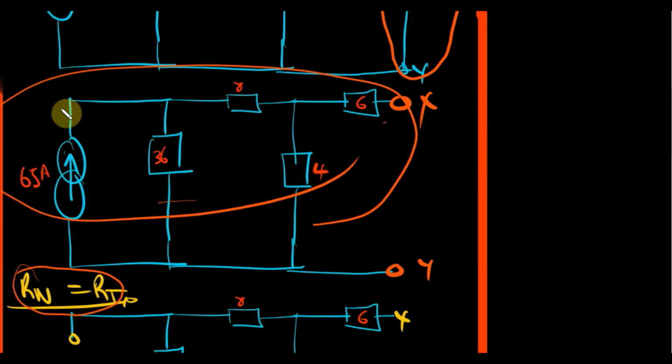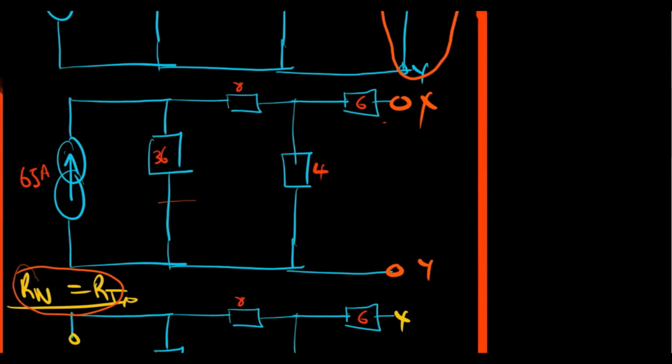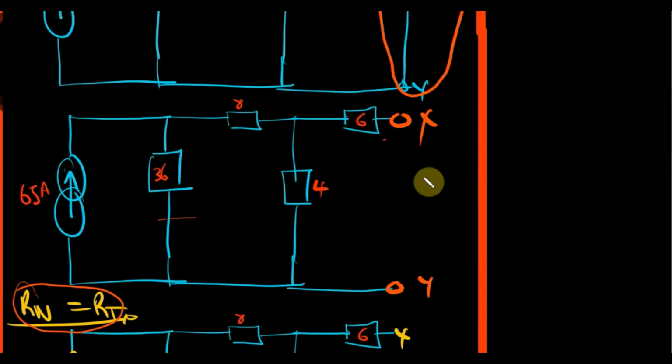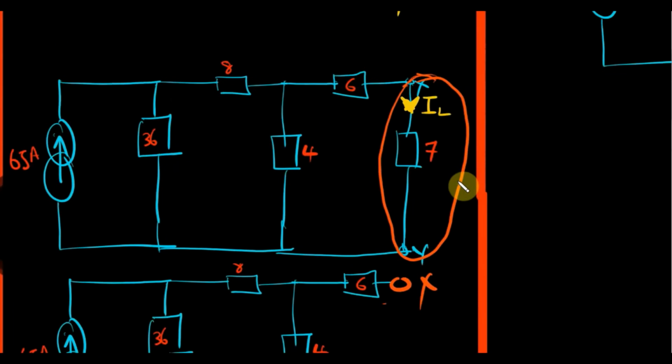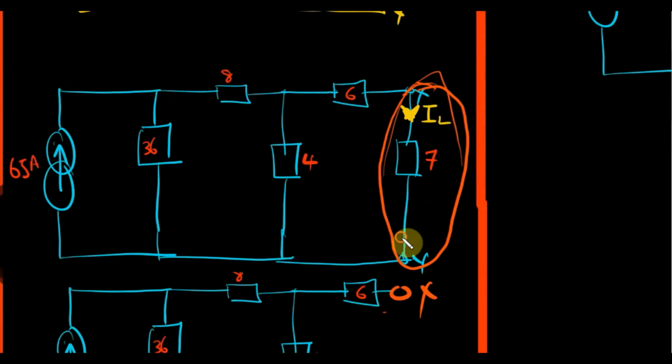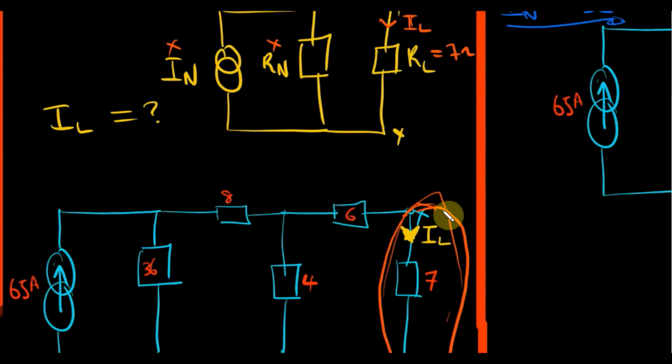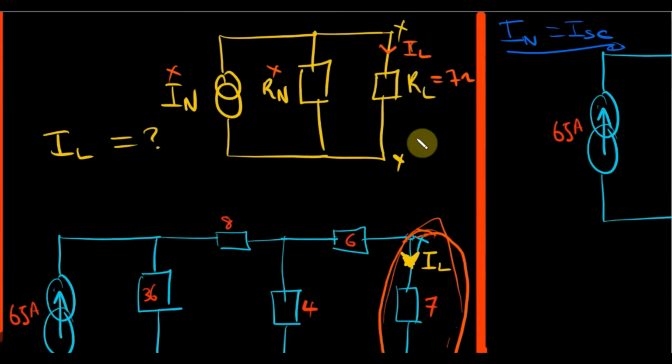But before doing that, before you go to combining resistance, take the load resistor and attach it to the Norton equivalent circuit.